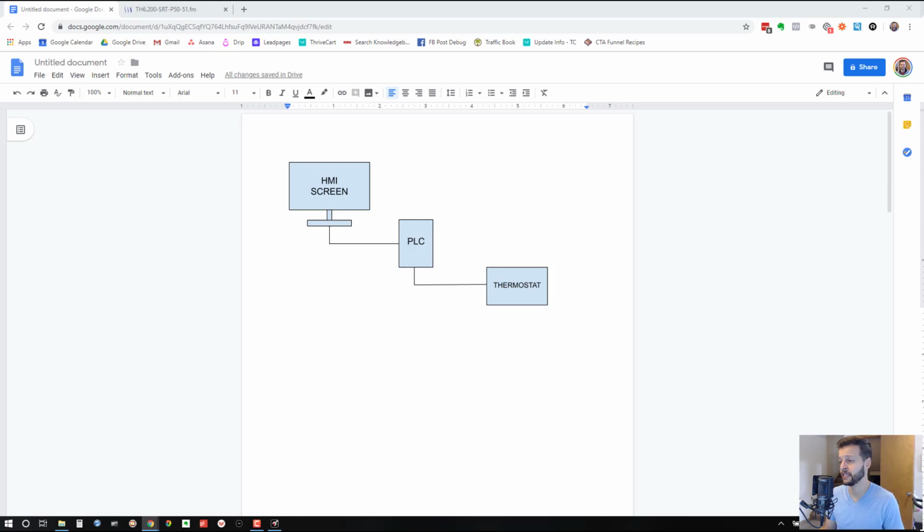So Modbus is an old industrial communications protocol, and it allows for the transmission of data among PLCs and/or other industrial devices like drives or power meters. And believe it or not, this protocol has been in use since 1979. So it's obviously stood the test of time, and this is most likely because of how simple it is to use and the fact that it is open source, meaning any company or individual can build Modbus communications into their PLC products or other industrial devices that they're developing. So a lot of people have done that, and over time it's become one of the industry standards for industrial